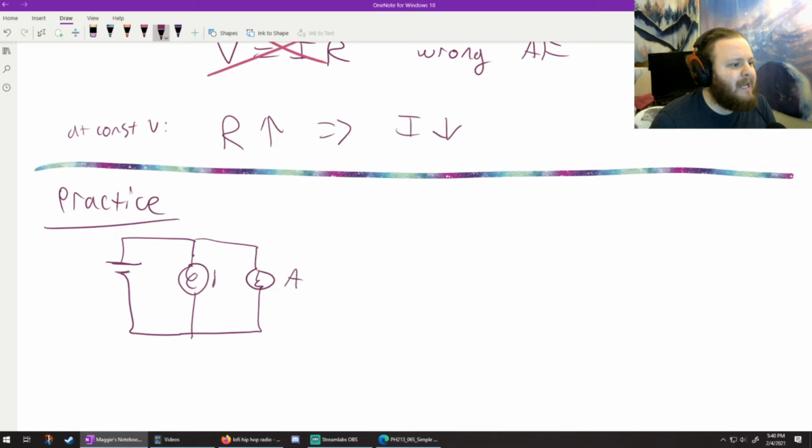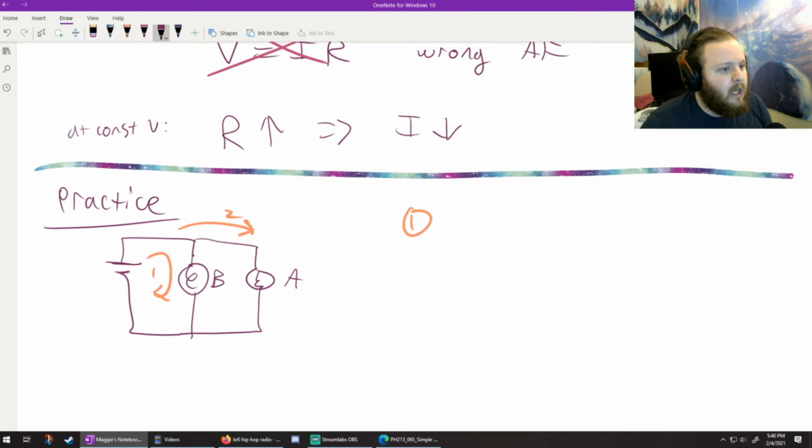All right. So, can we say anything given this situation about the potential difference across light bulb A and light bulb B? Well, let's draw some loops. I'm going to draw little circles for 1 and 2 going around the outside. So for loop 1, I can write down the loop law. I'm going to encounter a potential V0 coming out of the voltage source, and I'm going to hit that first. So I'm just going to start over here in both cases, right beneath the battery.